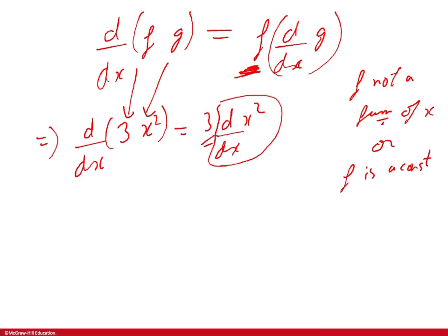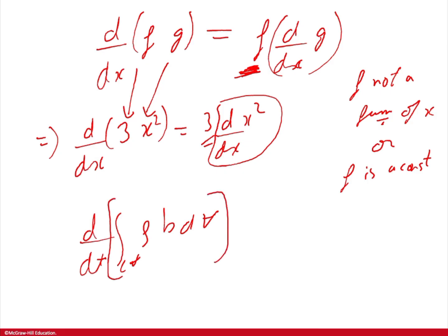Okay, so in the previous relationship you had d dt of the control volume integral of rho times b dV. Technically, you're taking the time derivative not just of density and not just of b, but also of the control volume itself, because it's inside the time derivative.